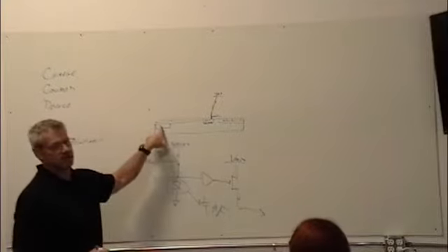If you don't do some sort of passivation, what happens is, as I shift from bucket to bucket to bucket, occasionally I'll leave an electron behind, because it'll stick there. But eventually he'll release. And then he'll free up, and then eventually maybe another one will stick.